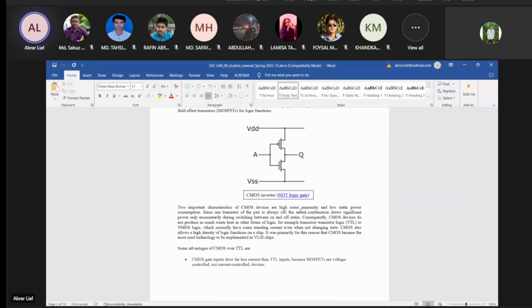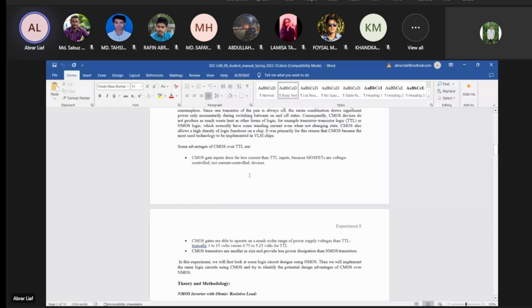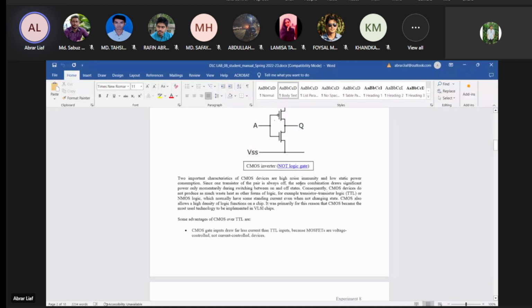Now there are also other devices, right? There is TTL, transistor-transistor logic, which you have learned about in your midterm syllabus. Then there is RTL, resistor transistor logic, and DTL, diode transistor logic. These different types of logic were used before the arrival of CMOS. The early computers were made using RTL, TTL, and DTL, because at that time we did not have such advanced technology to fabricate CMOS.